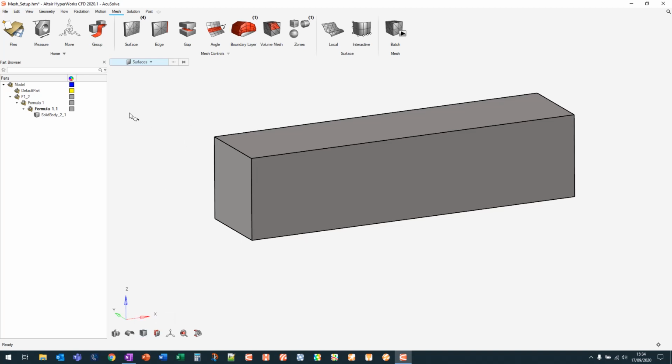If you want to see how many nodes are in the model, go towards the measure tool and press the entity count. You should see in here firstly how many points, lines, and surfaces are in the model, but also nodes.